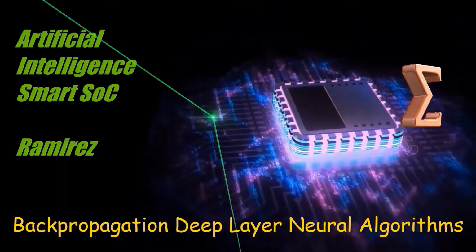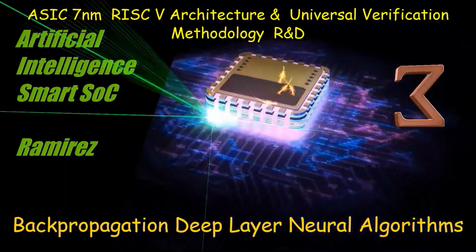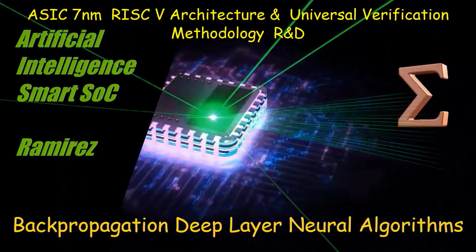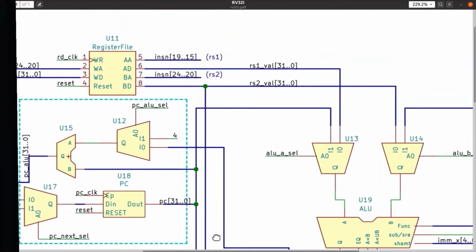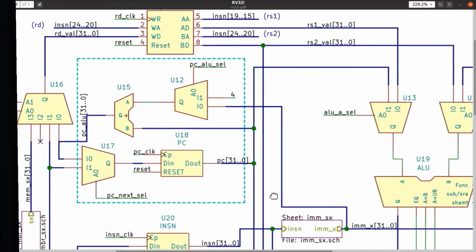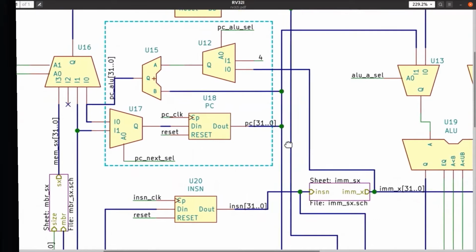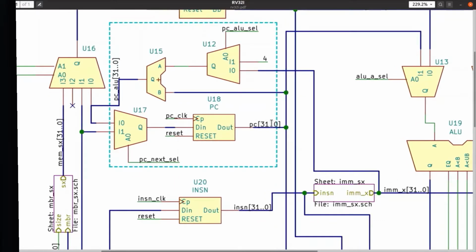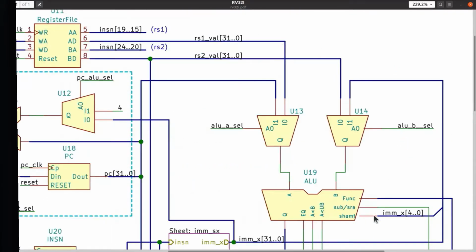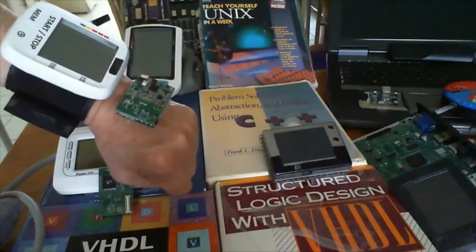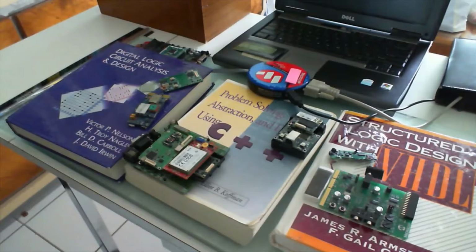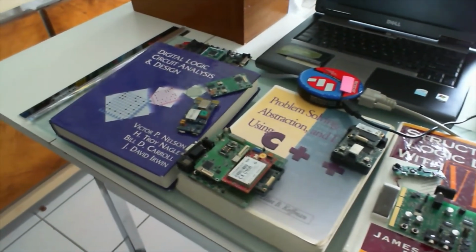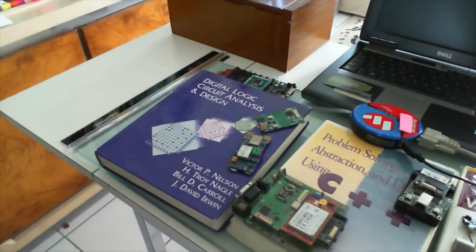For large macros such as multi-core embedded systems, where simulation speed in the system environment may be an issue, it can be useful to include cycle-based simulation and/or emulation models. In general, RTL that complies with the coding guidelines will work with cycle-based simulation and emulation.